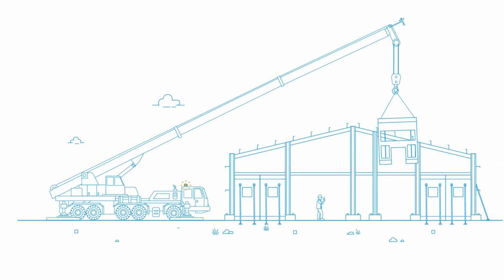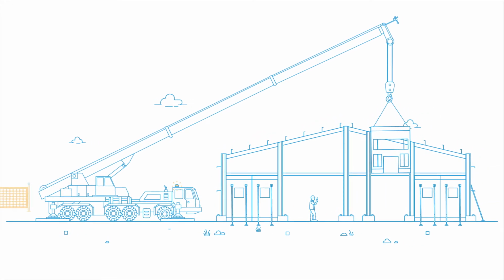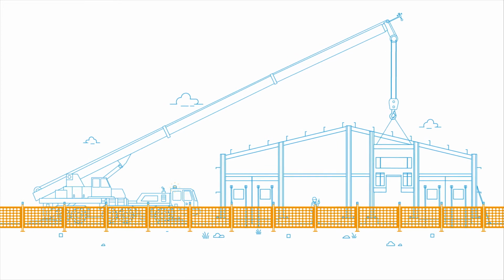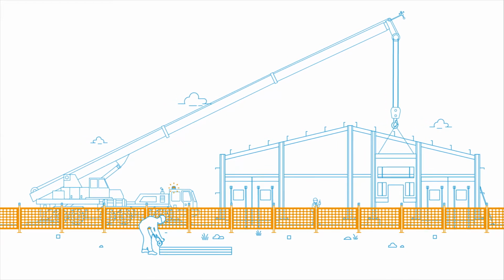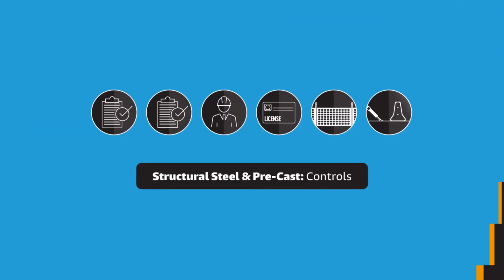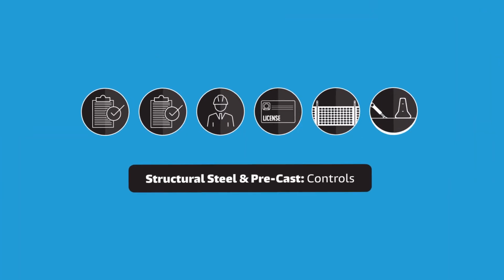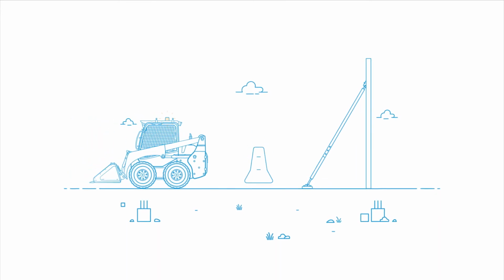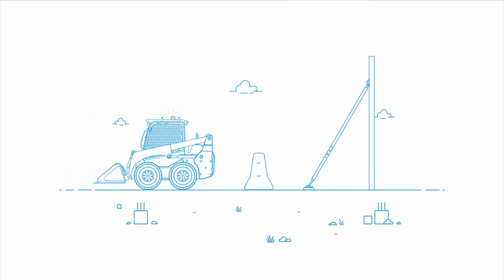During erection and dismantling of structures and supports, a strict exclusion zone must be maintained, with suitable barriers to restrict unauthorised access. And to protect temporary supports where potential significant impact is a risk, the appropriate physical protection must be in place.